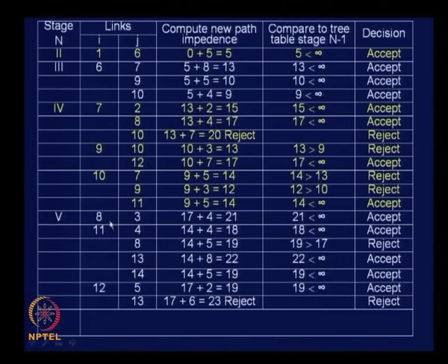So, from 8 we proceed to 3, the cumulative travel time already to 8 is 17, the 8 to 3 travel time is 4, the cumulative time is 21 to reach out to 4. It is less than infinity, so we are accepting. Also please remember this node 3 is another zone centroid. We are reaching the end point of interest in this particular case, right.